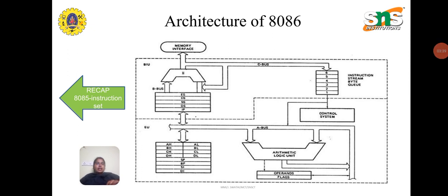To get a deeper understanding, first we can discuss the bus interface unit. It provides the interface of 8086 to external memory and input-output data via the system bus. It performs various machine cycles such as memory read, input-output read, etc. to transfer the data between the memory and the input-output devices.